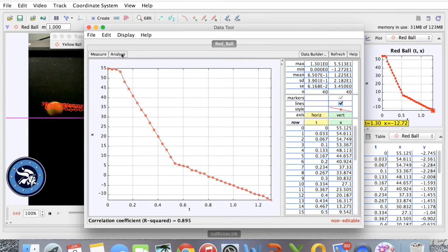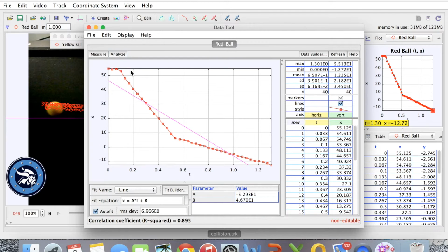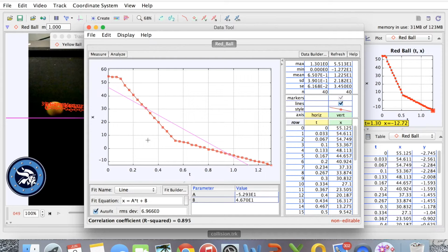Additionally, one of the most useful things you're going to want is actually the curve fitting tool. So what you do is you select this curve fitter, and it provides you with this trend line, which describes all of the data. As you can see here, it's a bit messy for us because we have a linear looking trend here, and then a decreasing trend here.